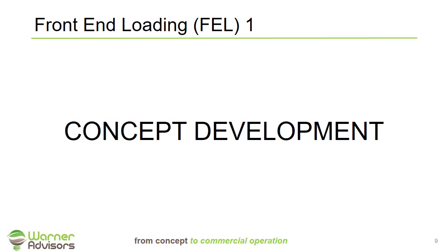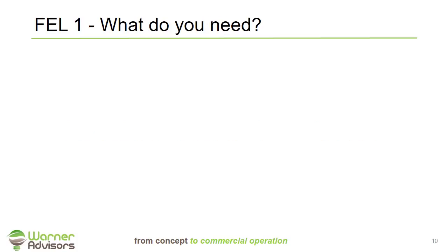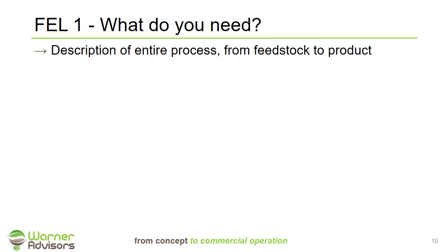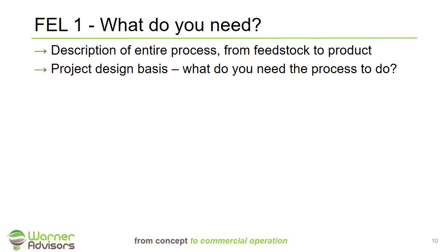So let's move into a more detailed discussion of front-end loading, or FEL1, which is the concept development phase of the project. If I'm ready to move into the FEL1 process, what am I going to need? First, I'm going to need a description of my entire process, from the feedstocks I'm going to use all the way to the product I intend to make. I'm going to need a design basis. What do you need the process to do?